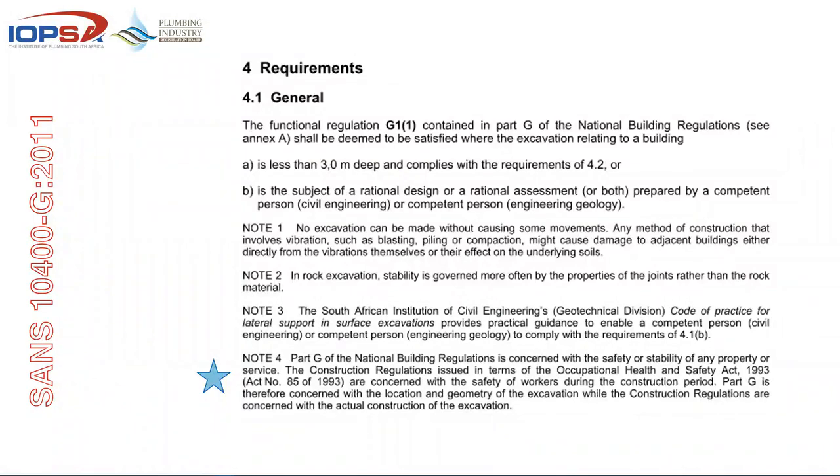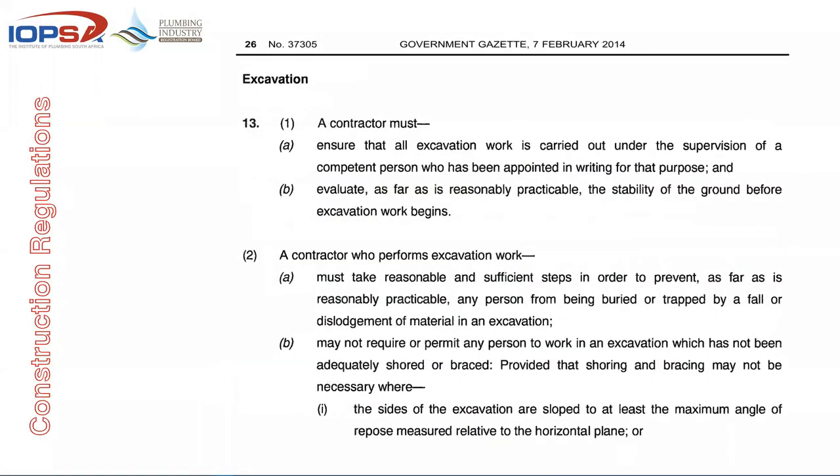If I could move on to this construction regulation of 2014, it is actually a free PDF download. You'll see it deals with electrical tools, various types of safety, transport of material, et cetera. So as far as excavation for the plumber is concerned, a contractor, in other words all of us, must ensure that all excavation work is carried out under the supervision of a competent person who has been appointed in writing for that purpose. Evaluate, as far as reasonably practicable, the stability of the ground before excavation.